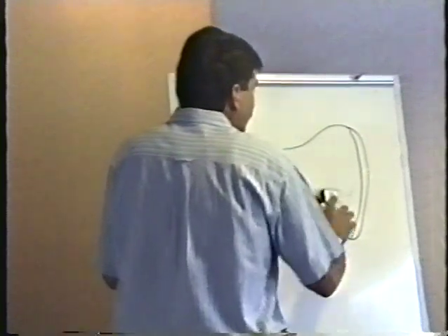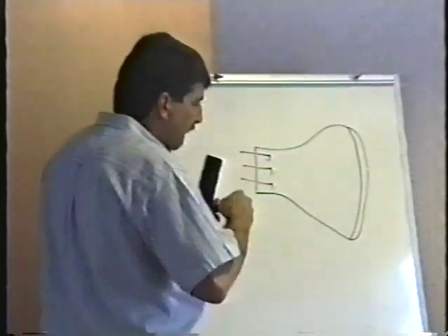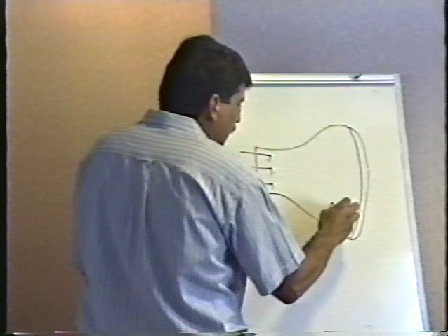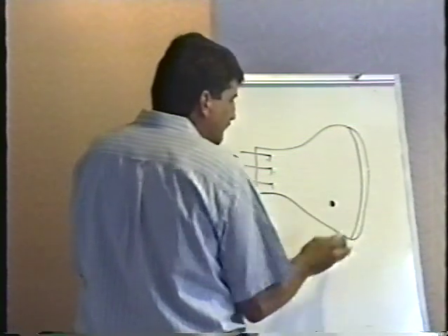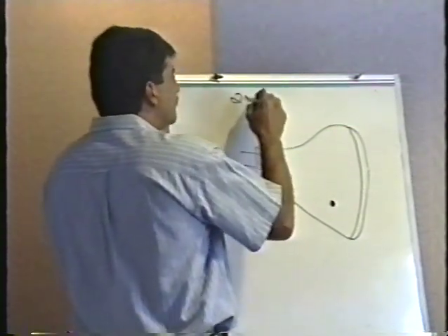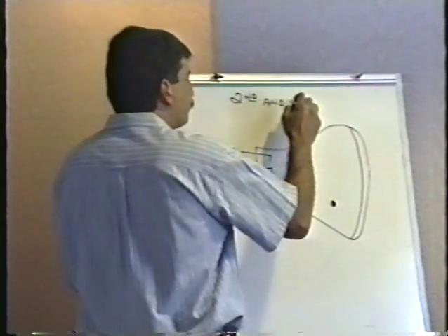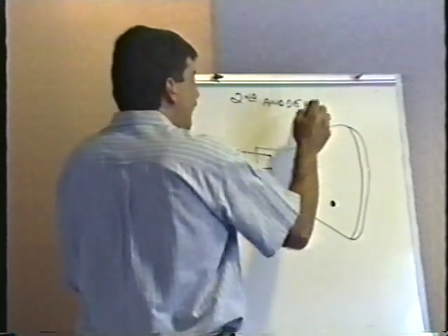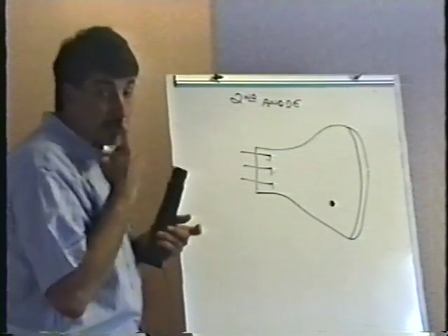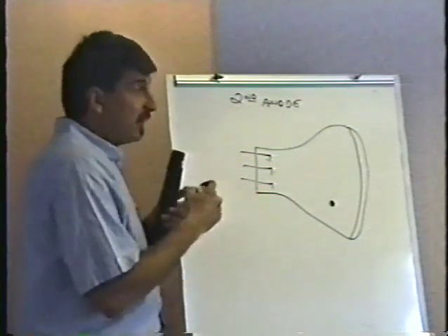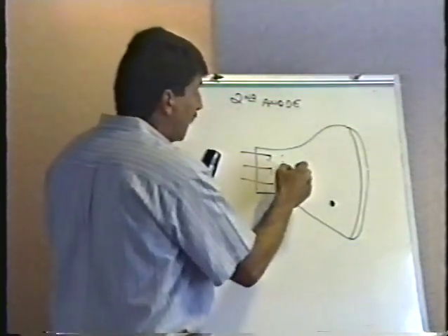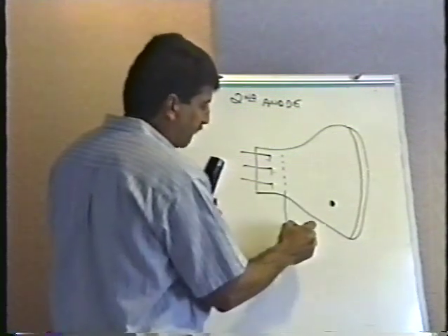On the side or the top of the picture tube, there's a small metal plug that's molded into the glass of the picture tube. It's called the second anode. A-N-O-D-E, the second anode. And I'll show it to you shortly. The first anode is actually part of the electron gun assembly. The first anode isn't called first anode, though.